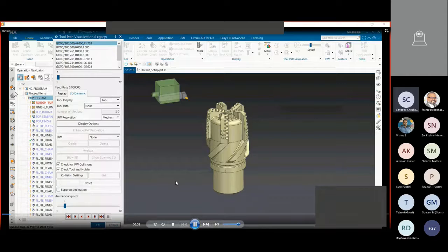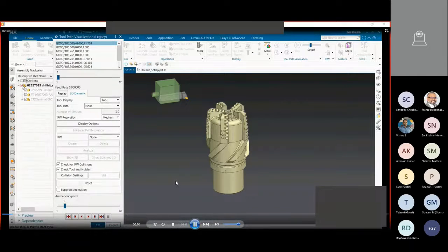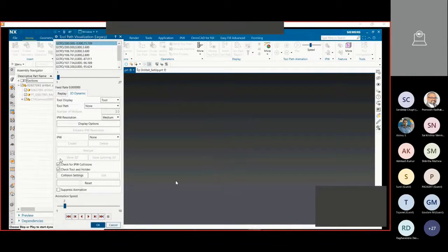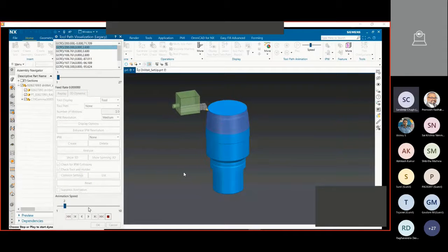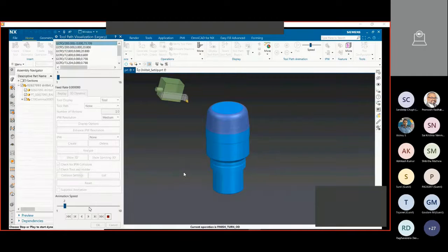So this is normal internal toolpath verification. You create the operations, and this is very common, like normal toolpath verification for any job. In NX, whether it is turning or milling, everything can be done in the same cycle setup, same MCS setup, same workpiece, and the in-process workpiece carries over from one operation to another.